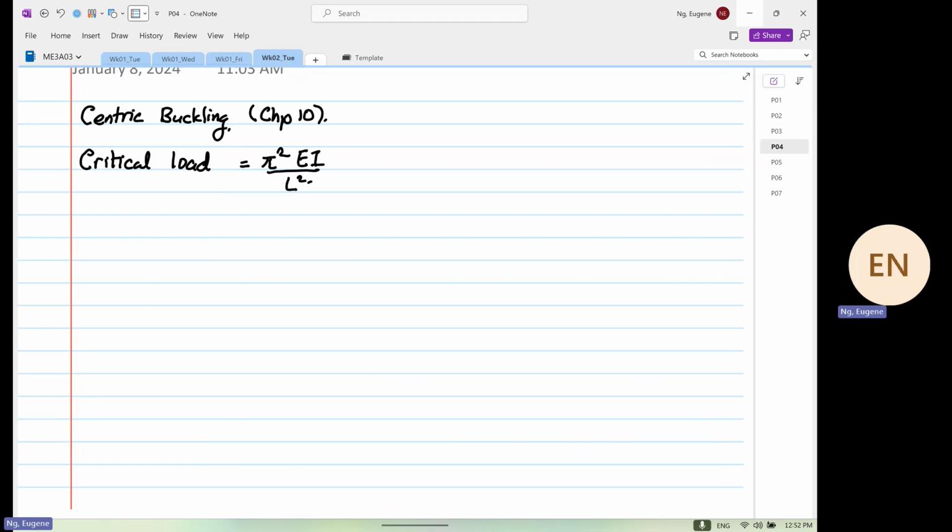So, buckling analysis: you only need to carry out buckling when the structure is under compression. If I were to give you a question that's under tension, and you do buckling, you know what I'll do to you? I'll give you 0 immediately. Are we clear? So a structure like this, under compression, then you need to carry out buckling analysis. Okay.